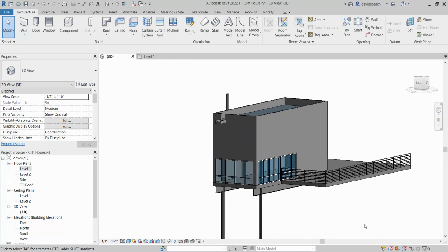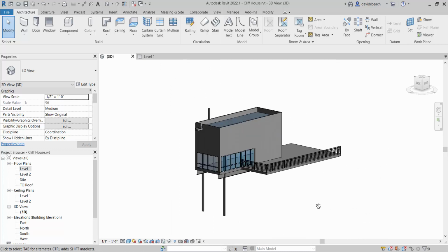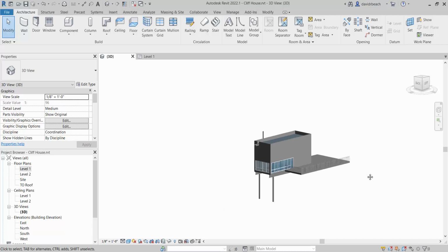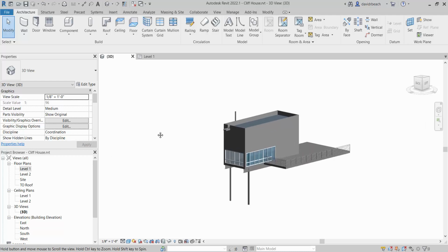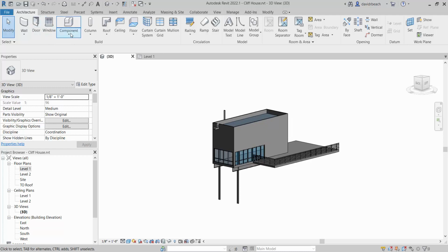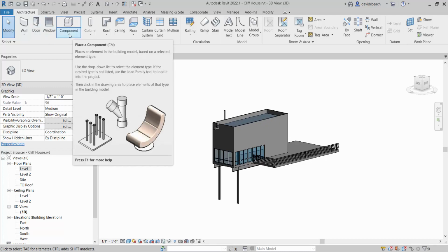And then, for the sake of getting this put together as a hidden line image inside of Revit, I really want to put some kind of ground plane in. I could take the time to build a quick topography, but frankly, I don't have that much time, nor the desire to build that. So I'm just going to build a great big generic model so that I can have a base ground plane in place. It's really easy to do, and I always recommend getting a ground plane in. We need something to catch shadows. We need something to reference eye height, those kinds of things.